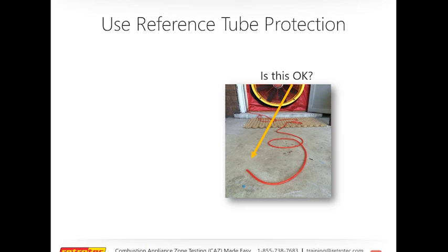So next, I want to talk about one of my favorite subjects, and that is the reference hose. Remember, when we were talking about gauge fundamentals, I emphasized how important it is to understand that what you're seeing is the difference between the reference and the input. And we just talked about where our reference and our input tubing will be. We also talked about how small a pascal is, how small an amount of pressure a pascal is.